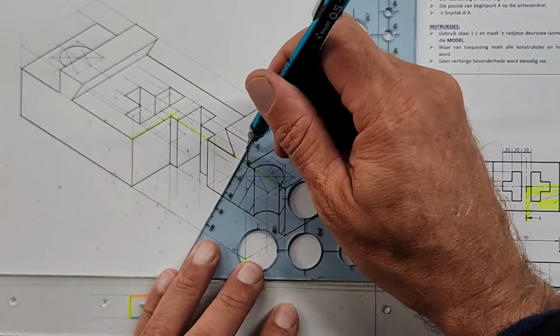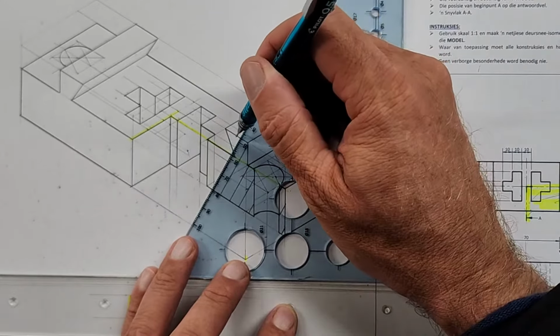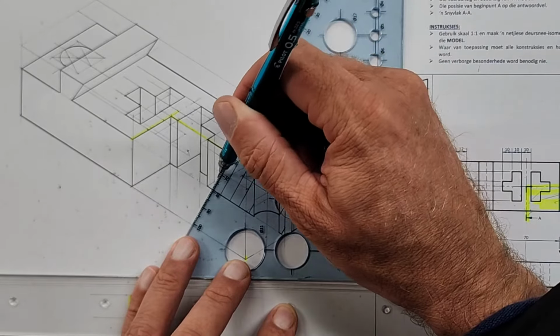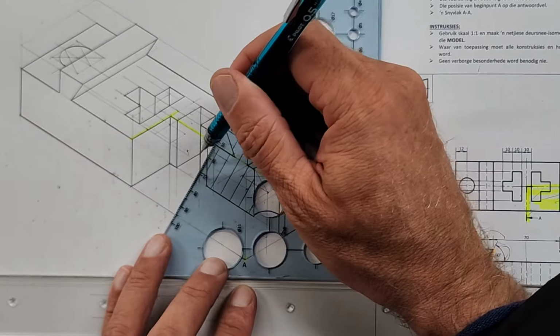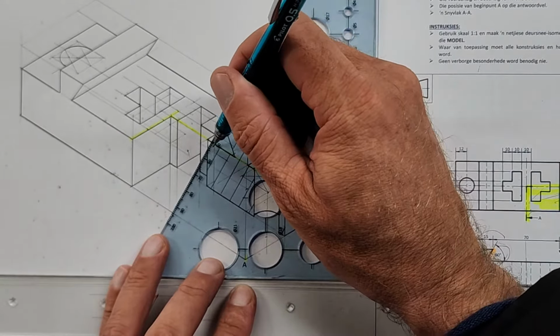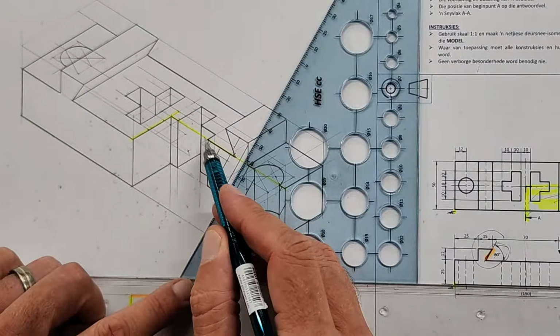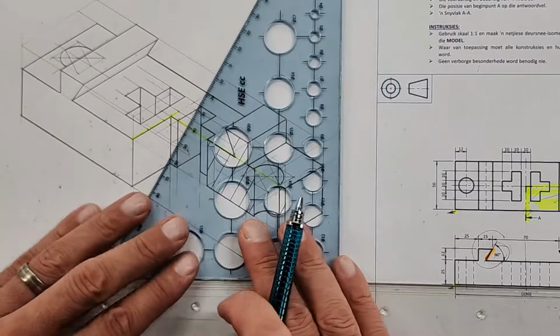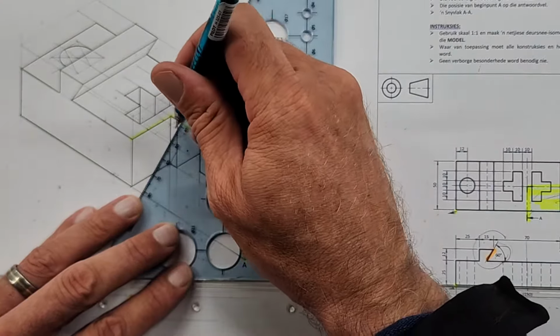There's one more thing that's missing on this drawing. Okay, so I only hatch where, if I had a saw and I cut through this, it would have cut into the material. Do I have to hatch this part here? Remember, this was air, right? So that hatching is going to stop here.